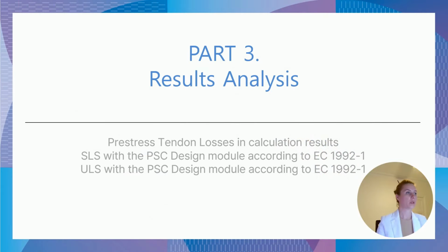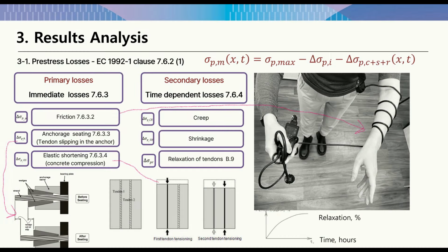We finally got through the modeling part. Now it's part 3, result analysis. So we asked MIDAS to analyze the structure. What's next? Let's consider pre-stress losses because they will significantly influence the internal forces of the structure.